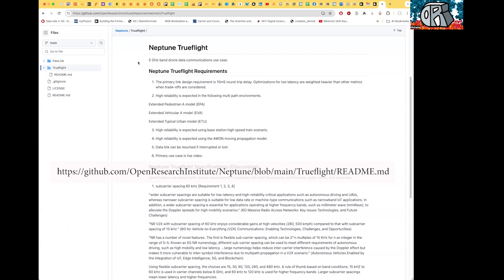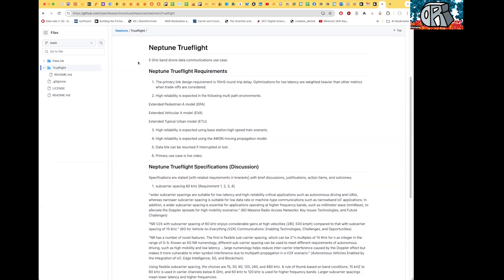So we know that there are radio frequency delays. And another aspect of latency or round trip delay in telecommunications is the delay from the user perspective. So there are equipment delays, and then there's the pure RF delay. When we talk about a latency requirement, we need to describe which one we're talking about. So the proposal here is a 10 millisecond round trip delay. This includes everything. This is from the user perspective.